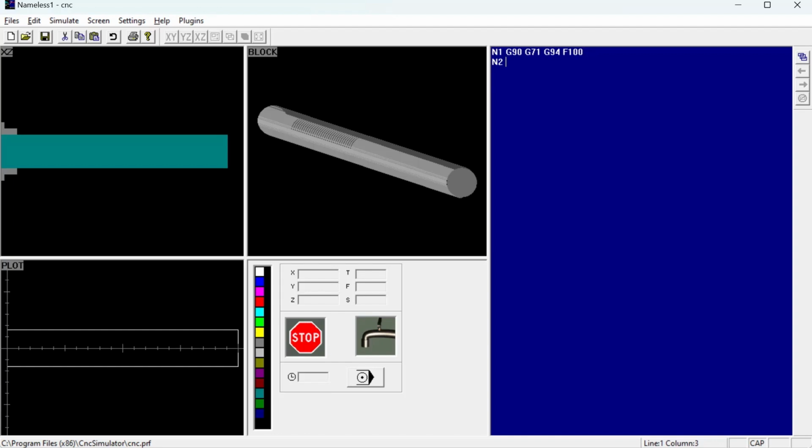Okay, so in the next line, we want the locator or the cursor to be placed at the origin. The code for that is G28. G28 allows us to locate or position the cursor at the origin or at any location. So the origin would be x0, y0, and z0. G28 is only used for the absolute coordinate system, so keep that in mind. And then next is the third line.